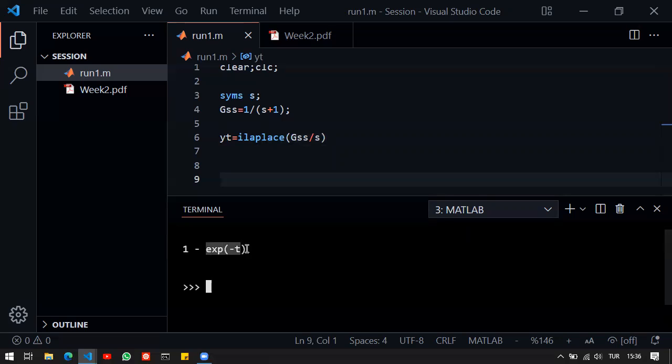And what I can see is I have an e term with the power of minus t. This is also the reason why I conclude that there will be no overshoot, because the gain of this for any t does not equal a bigger value than 1. So its absolute value is at max 1, and it is decreasing, by the way. Since this is 1 minus e to the power of minus t, as t increases, this term decreases and it will settle down to 1.